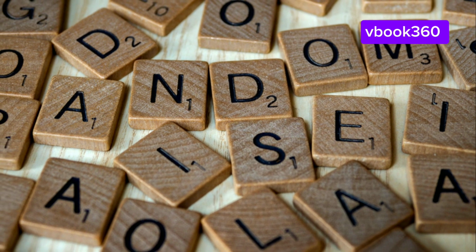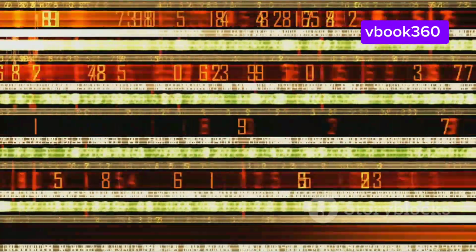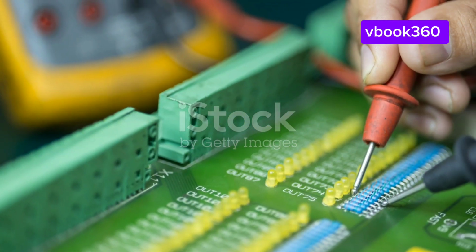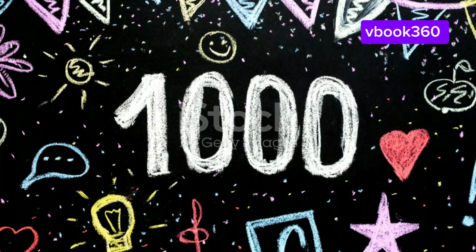For instance, black times 1, no multiplier; brown times 10, red times 100, orange times 1000, yellow times 10,000, green times 100,000, blue times 1 million, violet times 10 million. To illustrate, consider a resistor with the following color bands: brown, black, red, orange. Brown first band represents the digit 1. Black second band represents the digit 0. Orange fourth band represents a multiplier of times 1000.